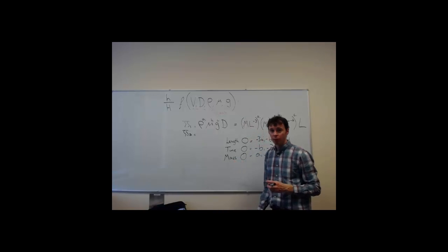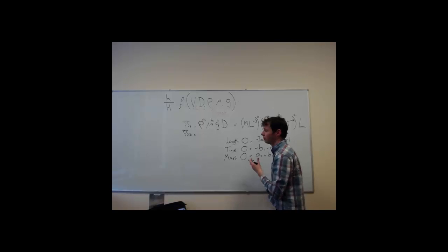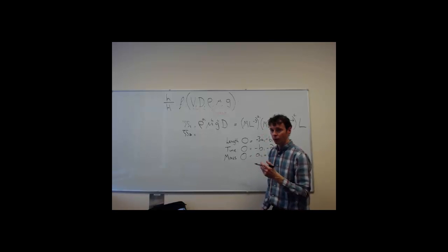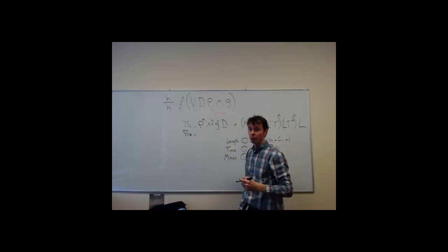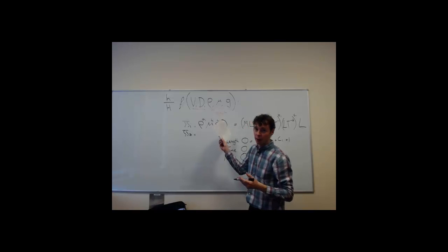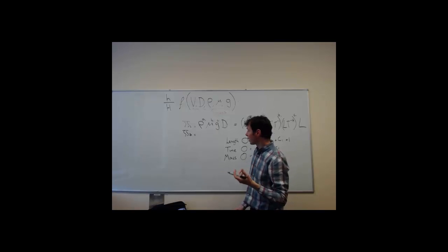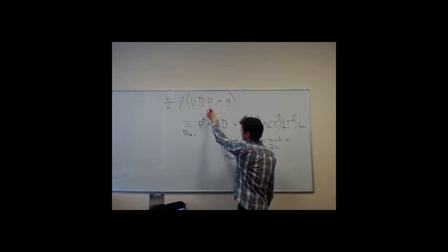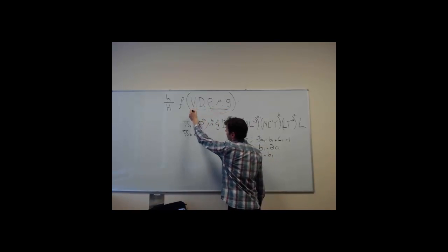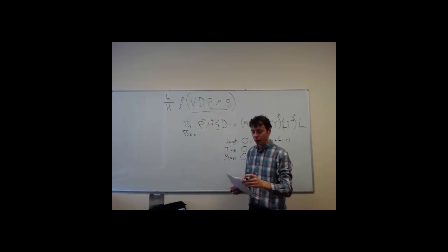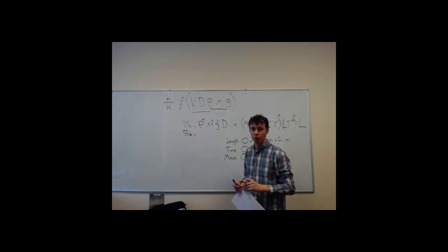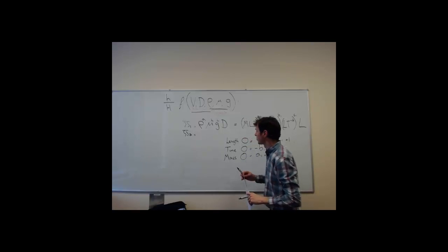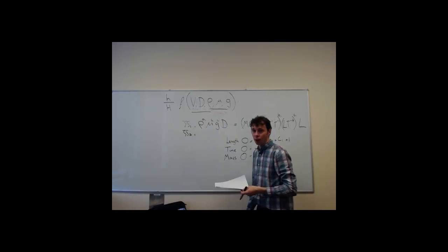Okay, and you'll come out with a dimensionless group if you do it properly, but it will be kind of less useful, probably more complex and involved than had you chosen easier repeating variables. So that's one of the ways it can be a bit complicated if you choose the wrong repeating variables. You'll still get a correct answer, it'll still be a dimensionless group, but it'll be slower to get there, and the group itself might be of a bit less use. Okay, but certainly your answer will still be dimensionless if you do it properly. Okay, so these three, definitely the wrong ones to repeat. But the first time round, like I say, with very little fuss, gave us a Reynolds number and the Froude number, which are two well-known dimensionless groups. Right, so that's Buckingham Pi applied to a very simple problem.